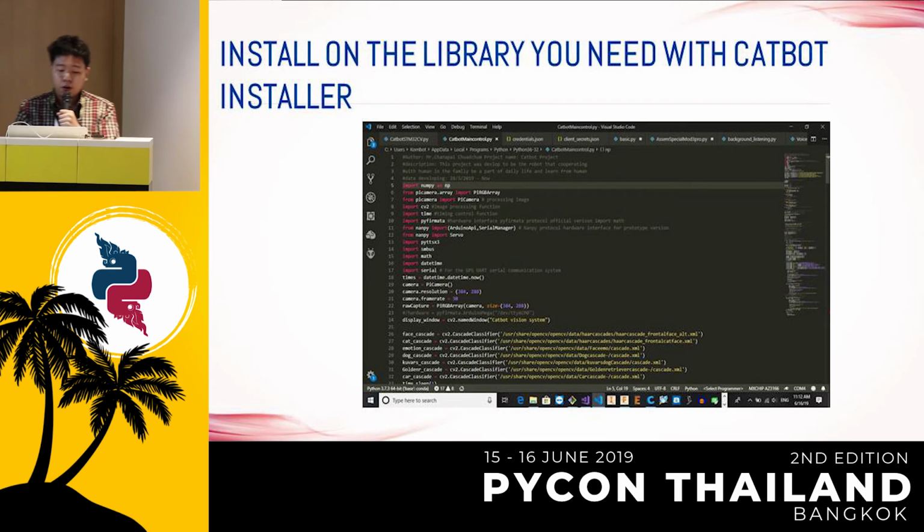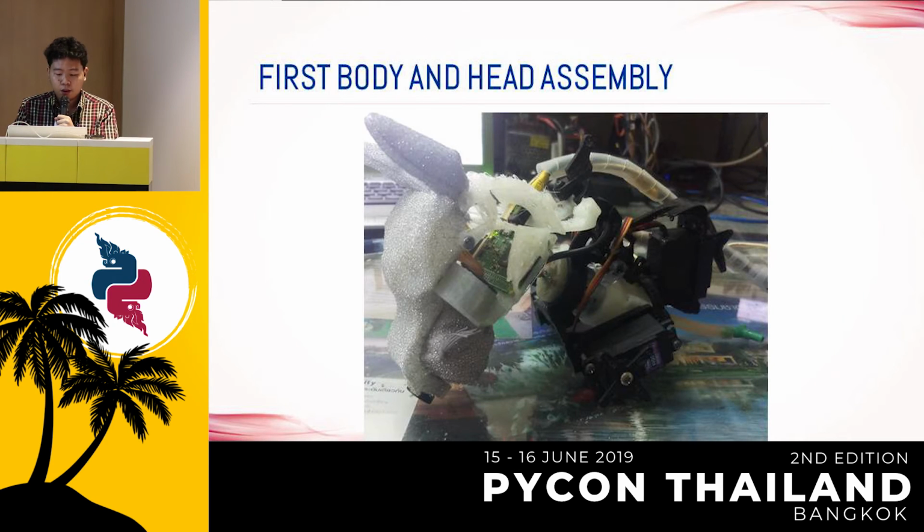So here is the instruction for how you are going to select the MCU and upload it. Okay, here it is. You just select the microcontroller that you are using. Okay, go on. And here's the setting, before you upload it, the upload method. We're going to select the mass storage. Let me show you something here.